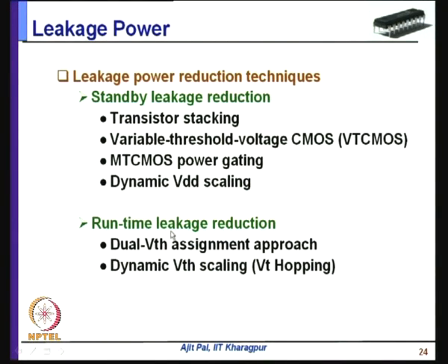However, nowadays in deep submicron technology, the leakage component has become comparable to dynamic power when the circuit is in operation. So, runtime leakage reduction has become important in present day technology.